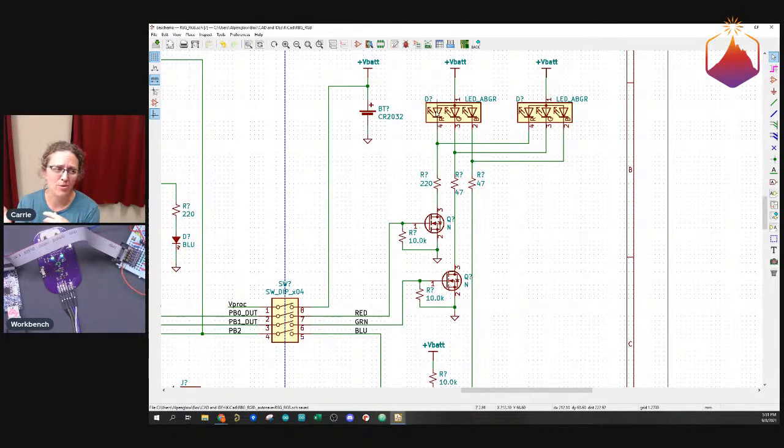I'd rather not have 3 extra parts that I have to buy and pay for assembly of as well. Resistors themselves are super cheap, almost free, but the assembly of placing that resistor on the board is not free. So that's actually what you're saving.